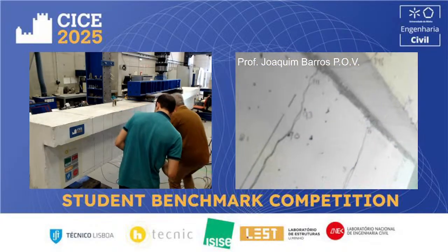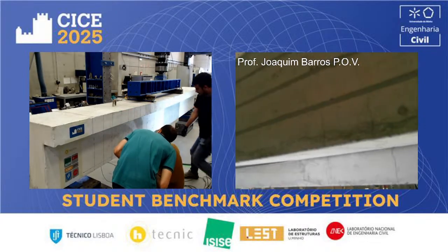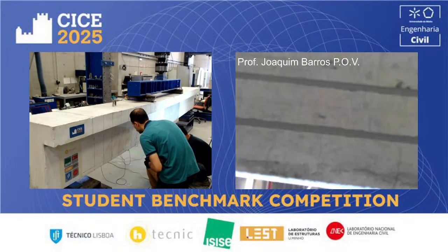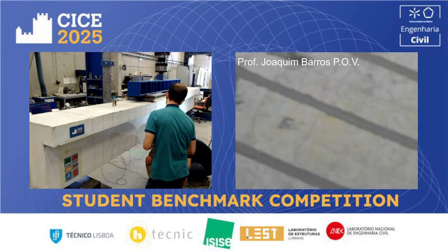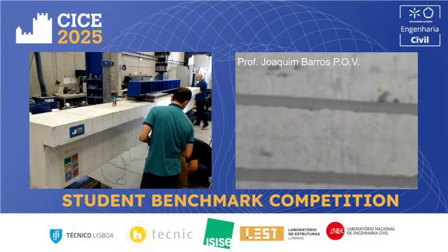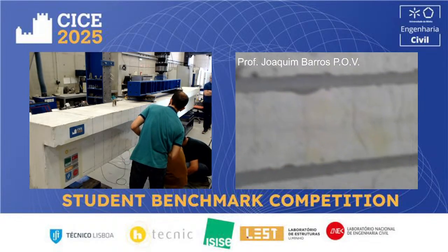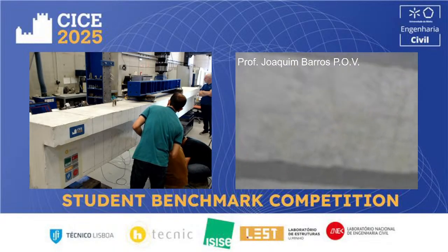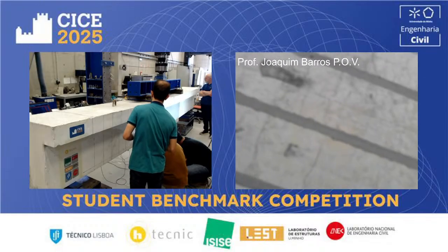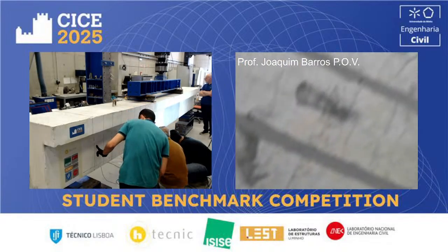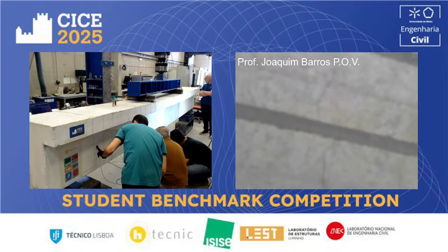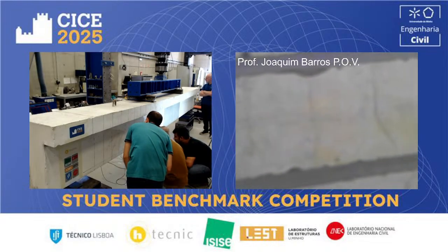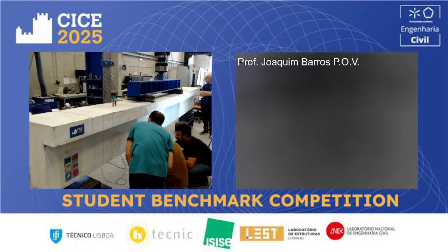Okay, I will show again the crack pattern in the bottom, so you can see the crack pattern. So it's a lot of cracks. Due to the debonding process between the laminates and the surrounding concrete, this huge number of micro cracks is formed. But obviously, where the cracks coincide with principal flexural cracks, the crack width is higher.